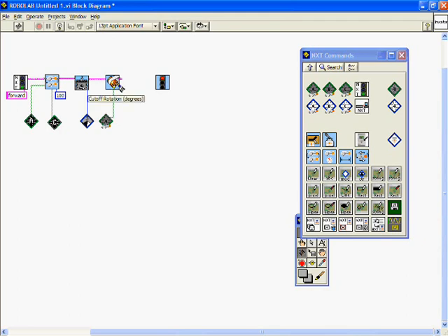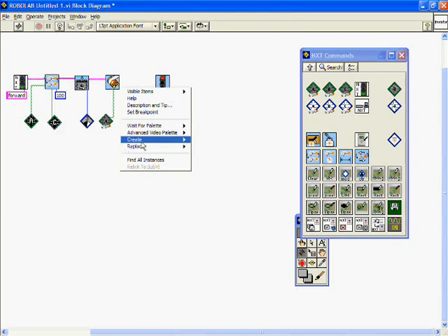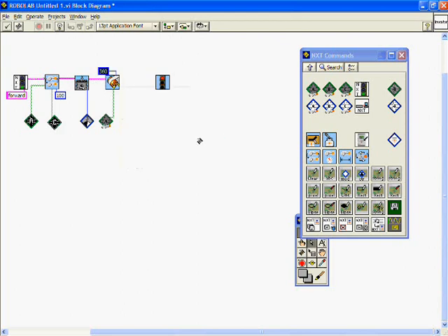The last port we'll look at is called cutoff rotation, which is in units of degrees. This is the number of degrees that the motor will rotate. Right click over this port, go to create constant. It's defaulted at 360 degrees, which is 1 rotation. Let's put in 2 rotations, which is 720 degrees. Double click and then put the number 720.